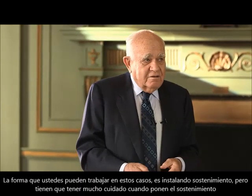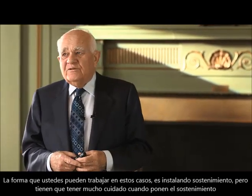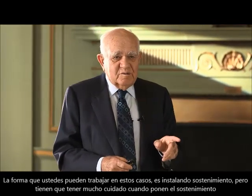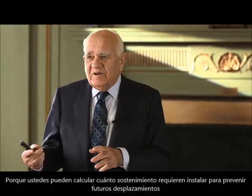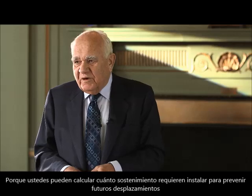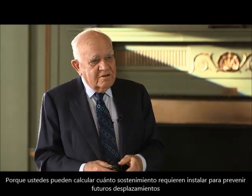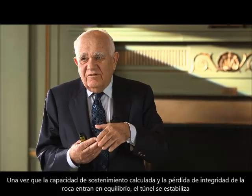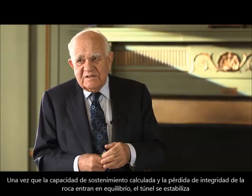And so the way you deal with that is by installing support. But you have to be very careful when you put that support in, because you can calculate how much support you need to prevent further displacement. Once your support capacity and the lack of capacity in the rock have met, the tunnel will be stable.